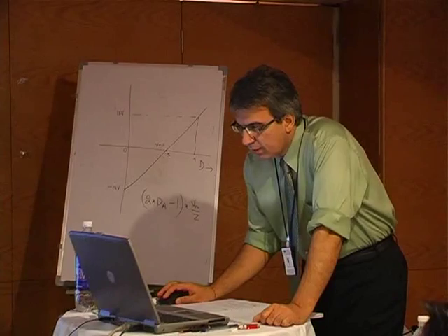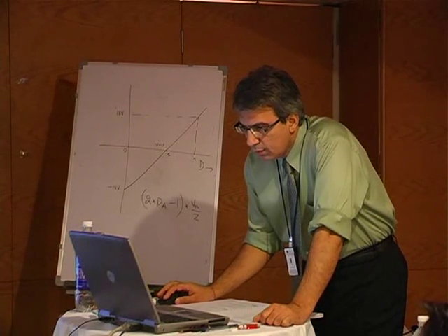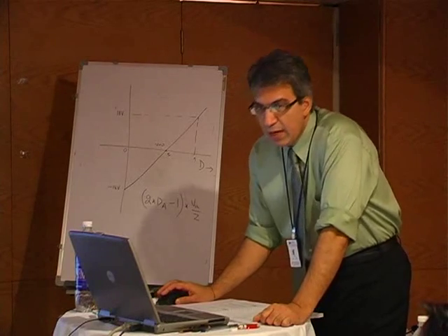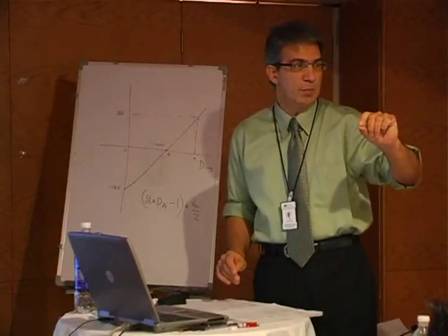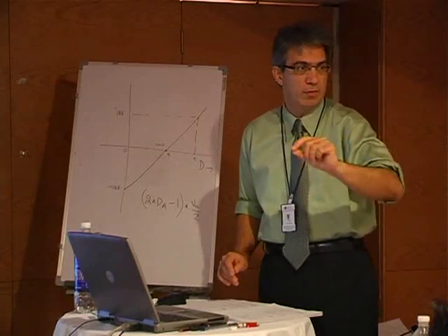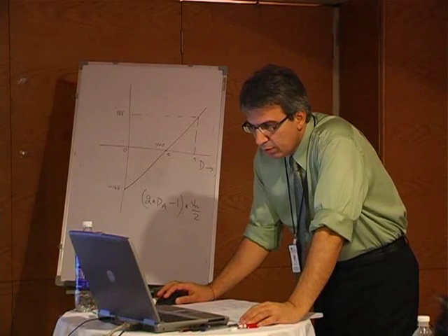Peak is about 179, 180 volts here, which is in line with an amplitude modulation of 0.9. So 0.9 times 200, that's where it is coming out to be. And then these frequencies which occur,